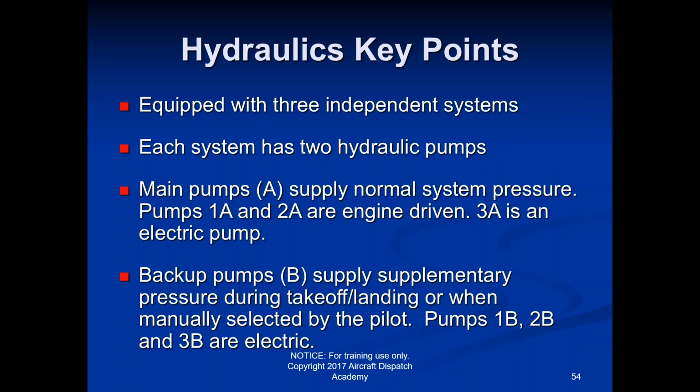Sometimes even without engine failure, the pump itself just doesn't work. In order to have the pump work, the engine does have to be on. But even with the engine on, sometimes the pump can still go out, just like any other pump. So sometimes you'll see an MEL for hydraulic system pump 2A, or one for system 3, like a 3A pump MEL or a 3B pump MEL, and depending on what those systems are hydraulically operating, you might see limitations on those particular things.